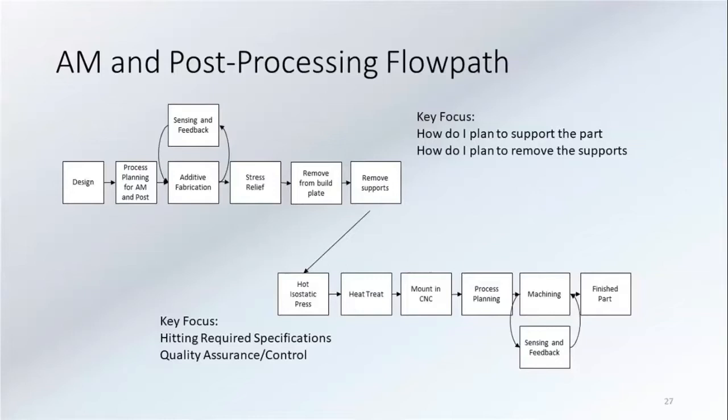A stress relief heat treatment step is unique. We typically will do that before we remove the supports, and that way when we cut the supports off, the part doesn't pop and potato chip on us. Then we'll remove it from the build plate, and then we'll remove the supports off of that. If you can build the part directly on the plates, then you don't need supports underneath it, and there's some tricks that we'll go into for some of this.